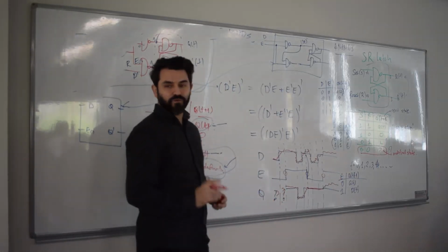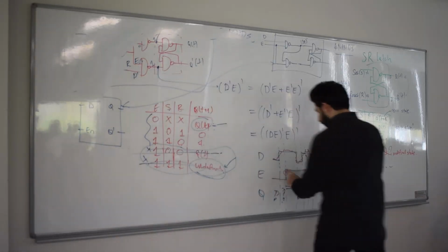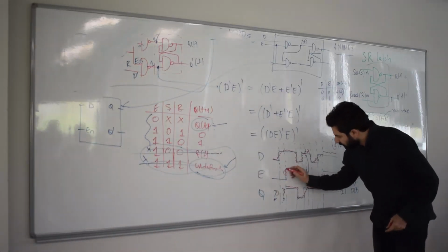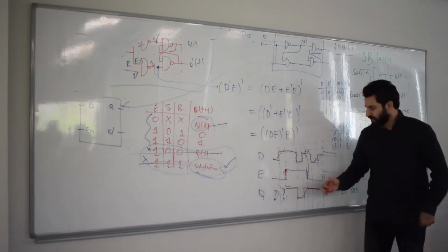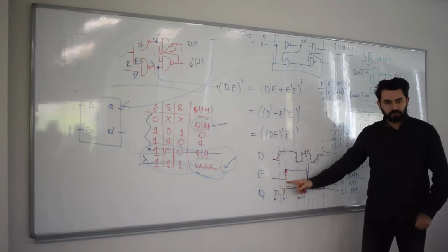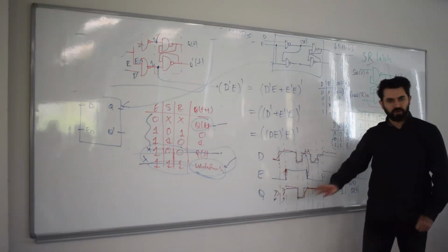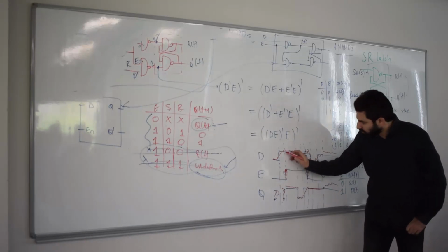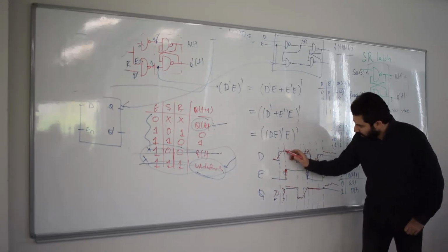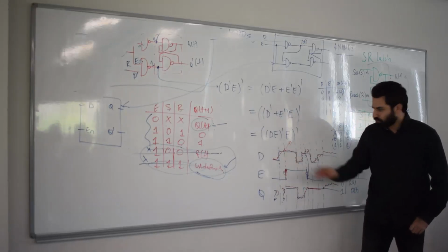What does that mean? For example, let's take the rising edge. Instead of the entire 1, we're going to take only the rising edge and make a decision. For instance, when enable is 0, we don't do anything. We just hold it, but there is no value to hold. It's just question marks. Whenever you have a rising edge, you go to that specific point in time, and you realize that this is your D. It's close to 1.